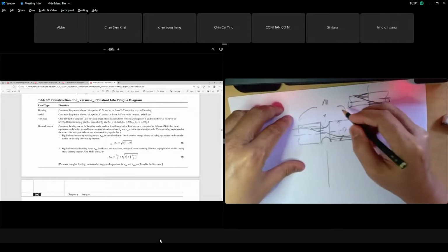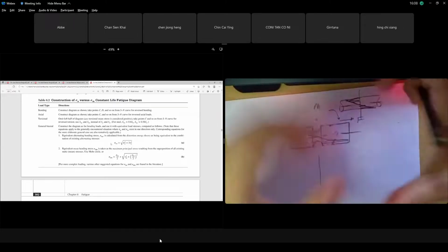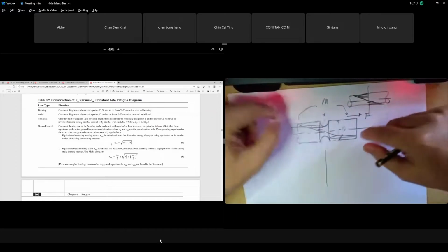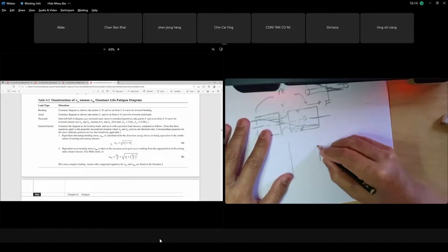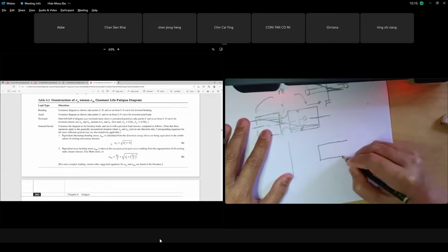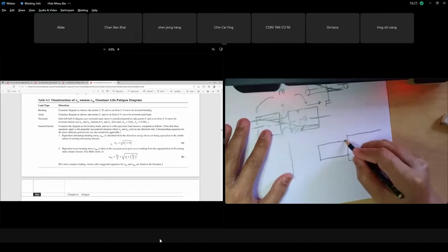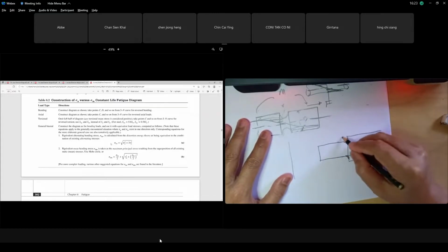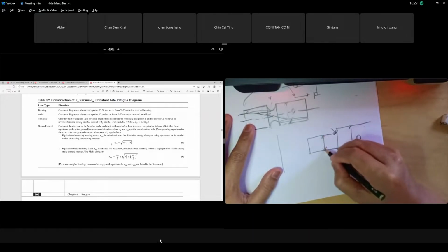You have bending like this, and also axial stress. With F axial, your stress distribution becomes so large because of that notch. Not just a notch on the groove, also in the case where you have a shoulder. Okay, you have a shoulder like this. You have a bigger diameter and a small diameter, with a radius here.